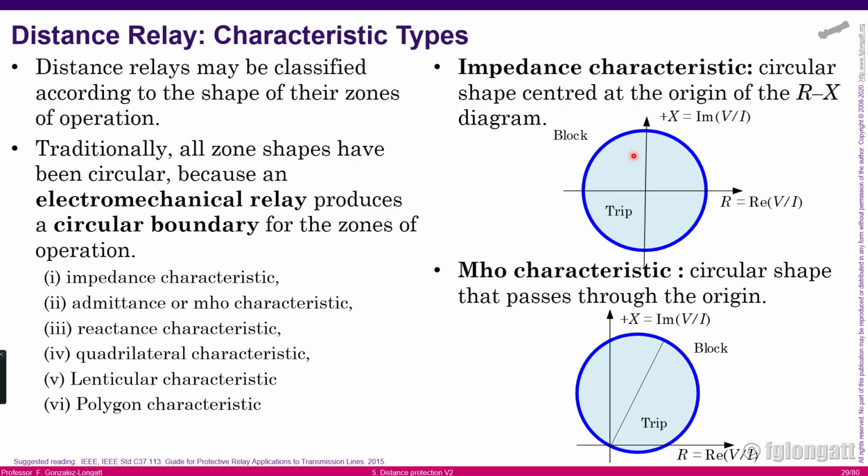The next characteristic is the mho characteristic. I remember during my second class, I was talking about operational characteristics of different relays, and I discussed the mho characteristic. The mho characteristic is quite interesting because it's used to introduce some directionality into the distance protection.